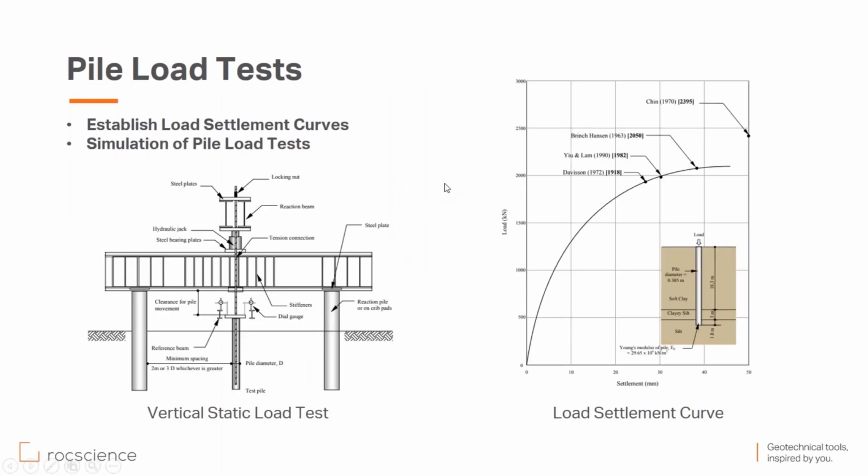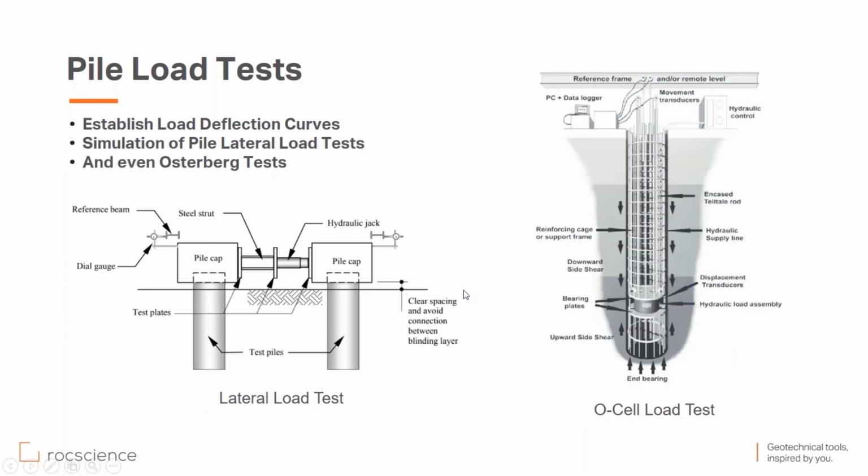Pile load tests also may be simulated by RSPile. So you can have a vertical load test, and you can simulate that one with producing a load settlement curve. You can produce a lateral load deflection curve if you have a lateral load test.